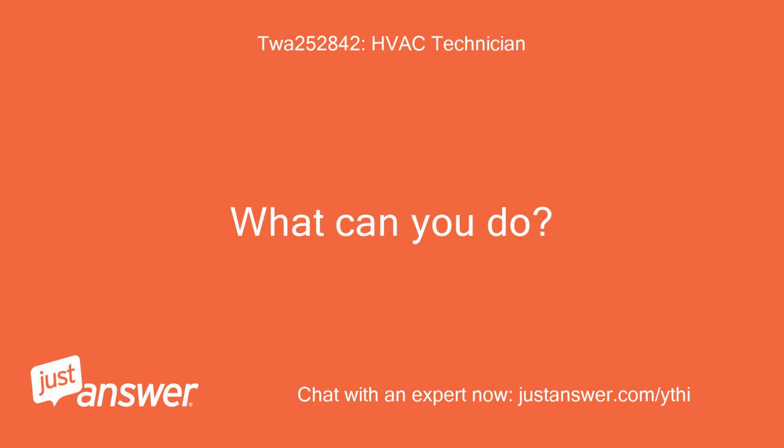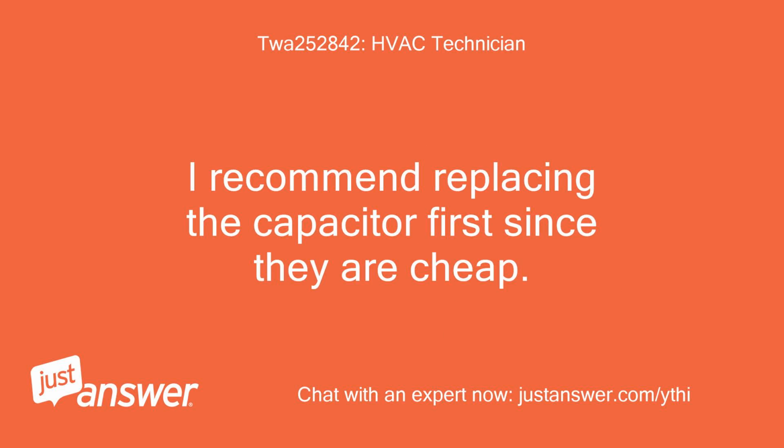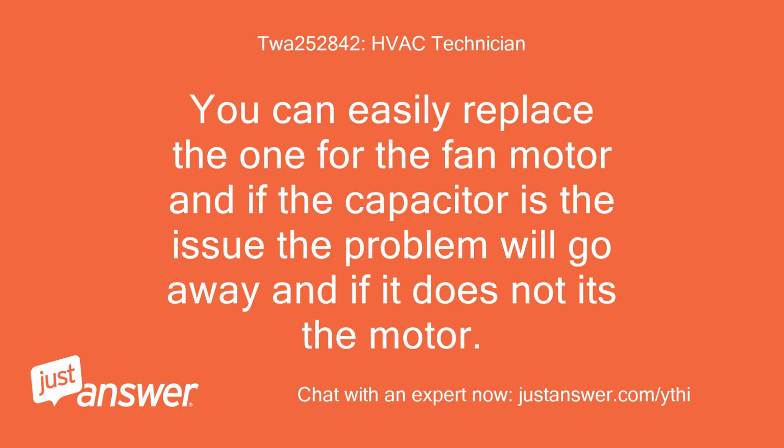What can you do? I recommend replacing the capacitor first since they are cheap. You can easily replace the one for the fan motor, and if the capacitor is the issue the problem will go away, and if it does not, it's the motor.